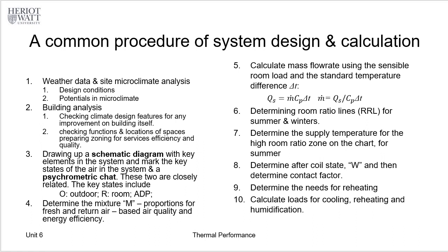Having done this, we need to check between W and the supply air temperature: if there is a gap, we need to reheat it. Remember, from W after the cooling coil, going into supply, there is sensible heating. There's nothing that can change the moisture content. And so therefore, that is the job for the reheater.